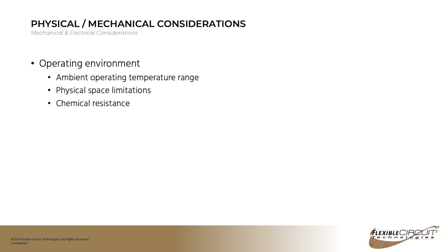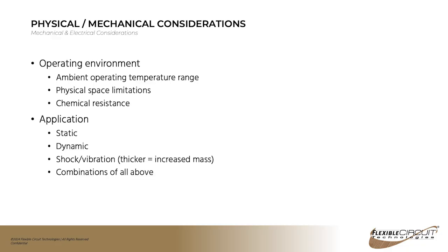You're also going to have to take into account physical requirements in your design that can be things like operating temperature, physical space limitations, and chemical resistance, and see how those will impact the overall package and design. The application, whether it's static or dynamic, shock and vibration can have an impact.